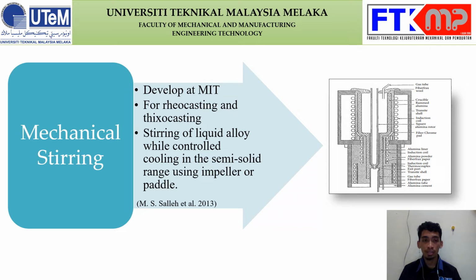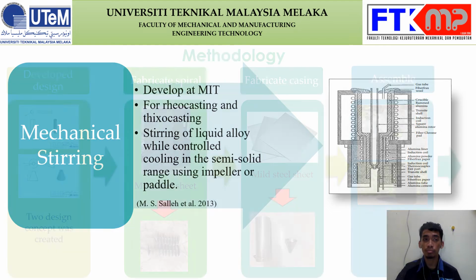The mechanical stirring technique was developed at MIT for rheocasting and thixocasting. This method stirs the liquid alloy while controlling cooling in the semi-solid range, using an impeller or paddle. For this technique, the stirring process can cause the risk of gas entrapment and oxidation.